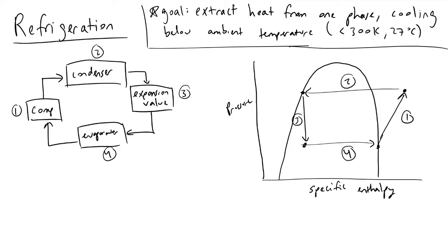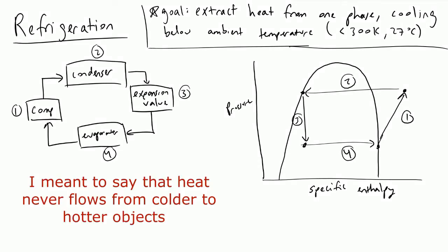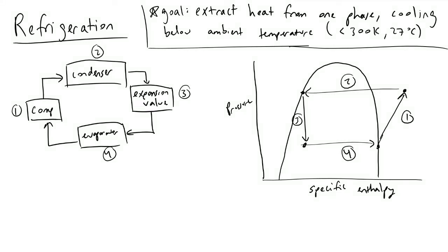slightly hotter. And as you're going through a thermodynamics course, you're also learning things such as heat will never flow from a hot object to a cold object. And so it can seem a bit counterintuitive, but fundamentally what's going on is we are making use of an endothermic process. And that endothermic process that occurs is the evaporation of some kind of fluid. And in your car, it's called Freon typically, and there's different types of Freon, such as R12 and R134A.